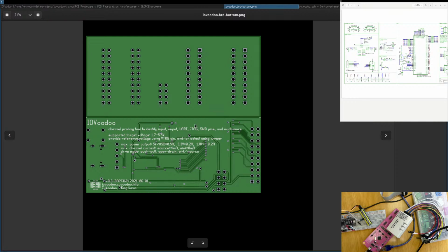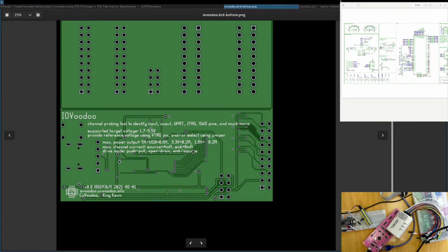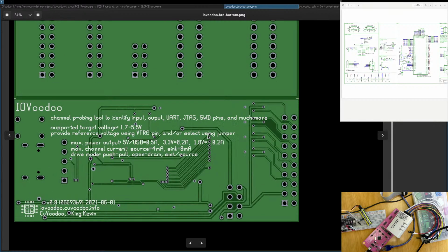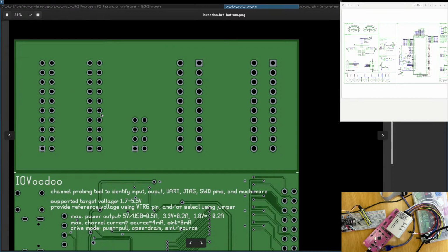I don't set it. Oh, here, source, for example. Here, this is kind of annoying. This could be corrected. We won't correct it. It's fine. I hope they will remove everything from the silkscreen. Everything which is not open, which is not filled in solder mask, should be removed in the silkscreen. Either you do it yourself or the fab house does it. And it's really important to check that because not all fab houses do it.